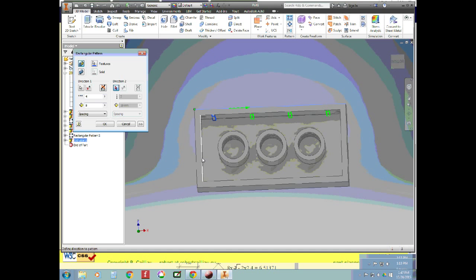And I think if I choose this inside, yeah, this will probably work better. Flip the direction. Make sure you choose the inside. And now, let's see. I want to go, that distance inside is going to be 15.8 minus 2.4. So let's start with that 15.8. Let's go minus the 1.2 wall thickness, whoops, might help if I put that minus in there. Minus 1.2 for one wall thickness, minus 1.2 for the other wall thickness.